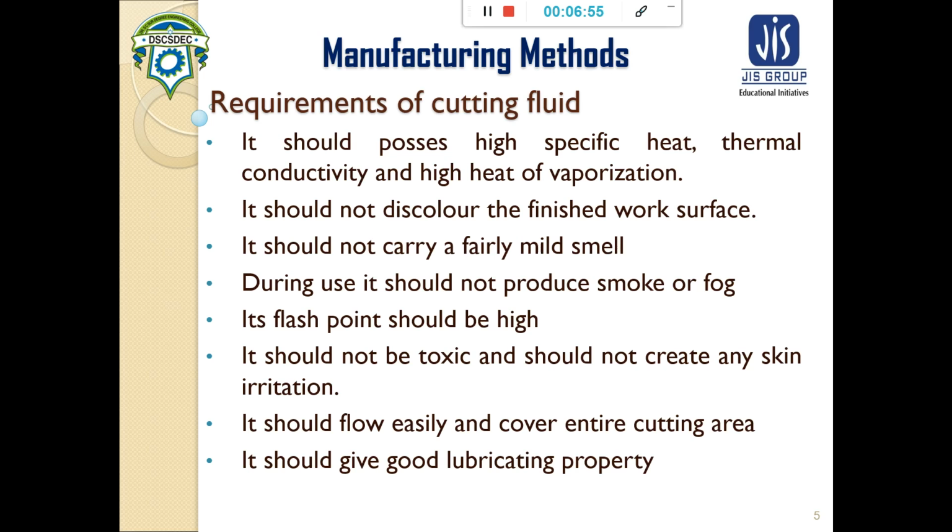So cutting fluid should possess high specific heat, thermal conductivity, and heat of vaporization. Why is high specific heat needed? Because one of the main aims of the cutting fluid is to cool the chip tool interface.